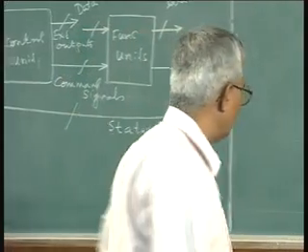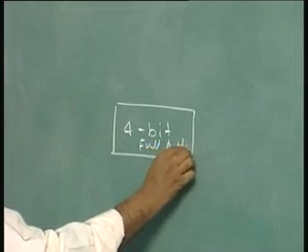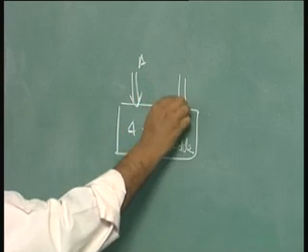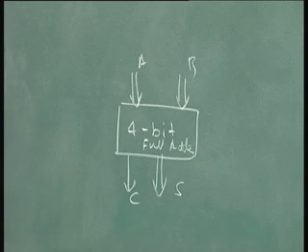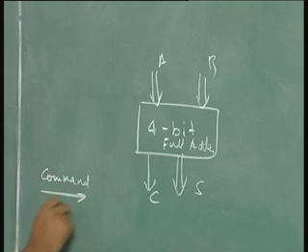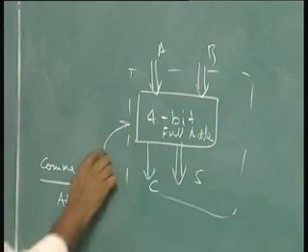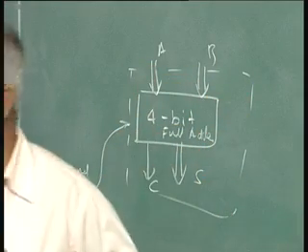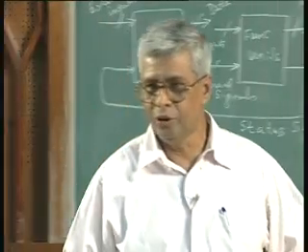Do you understand what I am saying? Supposing I have a 4 bit full adder. Please understand what I am saying. Now, this is A, this is B, and this gives me C or sum, and this is the carry. Now, there is no other control in this except power supply and ground. Now, I have a signal coming out from the controller called add. This has to go into this. Only when this comes, this should add these two numbers, otherwise it should not. It is not possible. I can't just control it, it is combinational logic. The moment I give the input, the output comes, how can I control it not to?